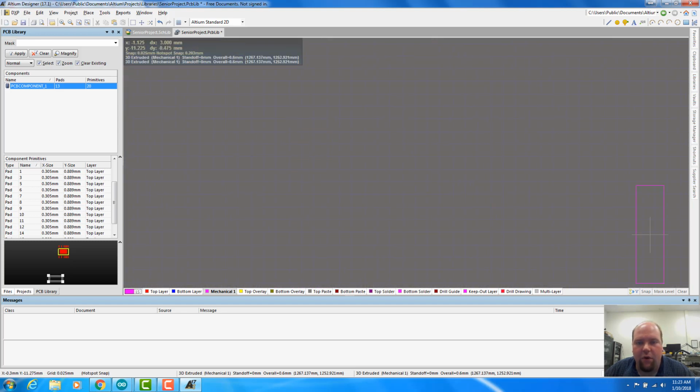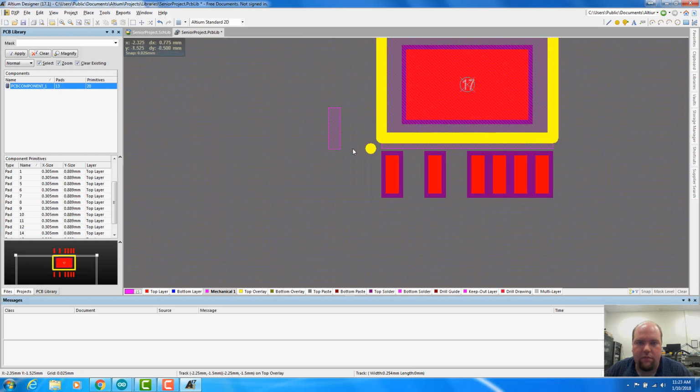So this is the part that I want. This is what I need. Now what I need to do is zoom out so I can see where I'm going. There, we got way away here. So now I'm just going to copy paste this guy. So I'm going to Control copy. Altium wants me to tell it when I copy something or cut something, before you make this go away, what reference on this part do you want to be where you're grabbing it from when you place it later on? So I'm going to just click the center here. And we'll move this guy into place.